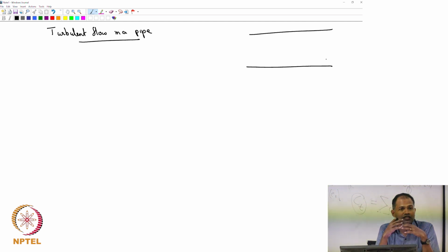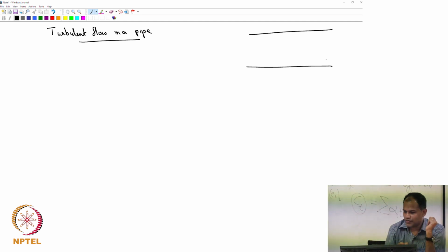And what we are going to see is that it's going to be a robust approximation, that the entire turbulent velocity profile given by the logarithmic law is a good approximation. But we have to do it and see that it's a good approximation. Okay, so I'm assuming that the entire layer is now just going to be given by the overlap layer law, or the logarithmic law. Or in other words, what will I write?